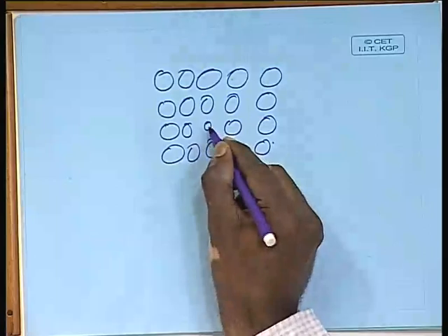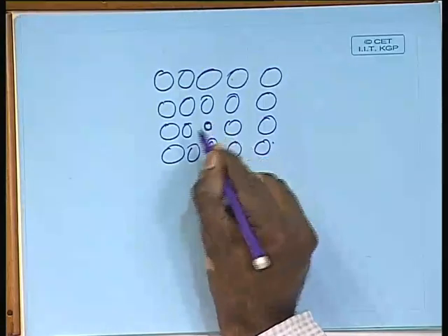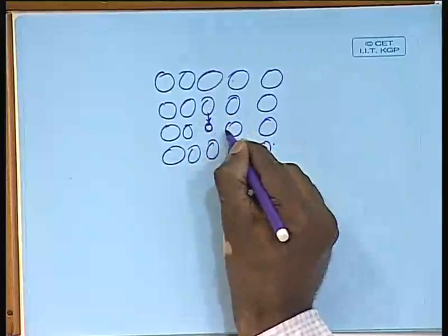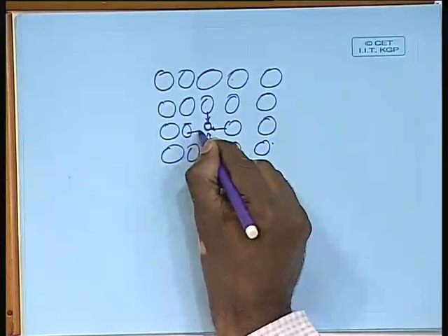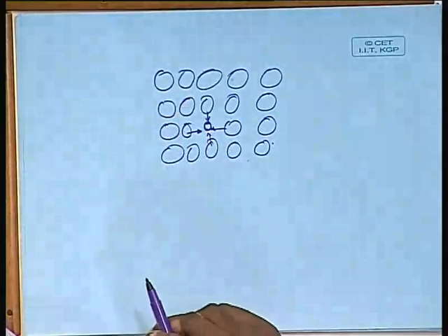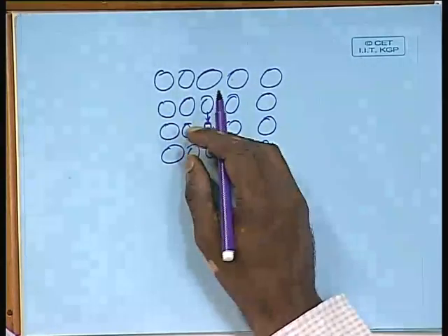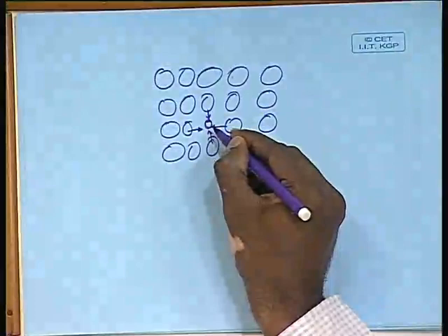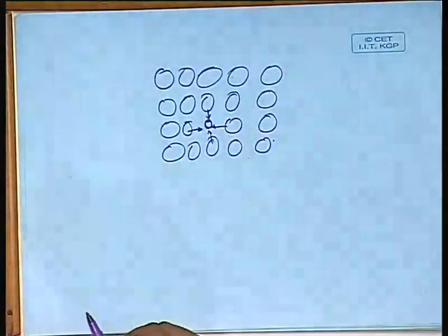remaining atoms, then you see that the moment you put a small atom there, the other atoms around it are attracted towards that, because there is always some kind of a delta H mixing associated with any A and B atoms, and because of that there is either an attraction or a repulsion, depending on whether delta H mixing is positive or negative. Okay, we know about it in the thermodynamics class, we have talked about it. And so if you look at such a situation, when the atoms are either attracted or repelled, there is some strain that is associated with it, okay.